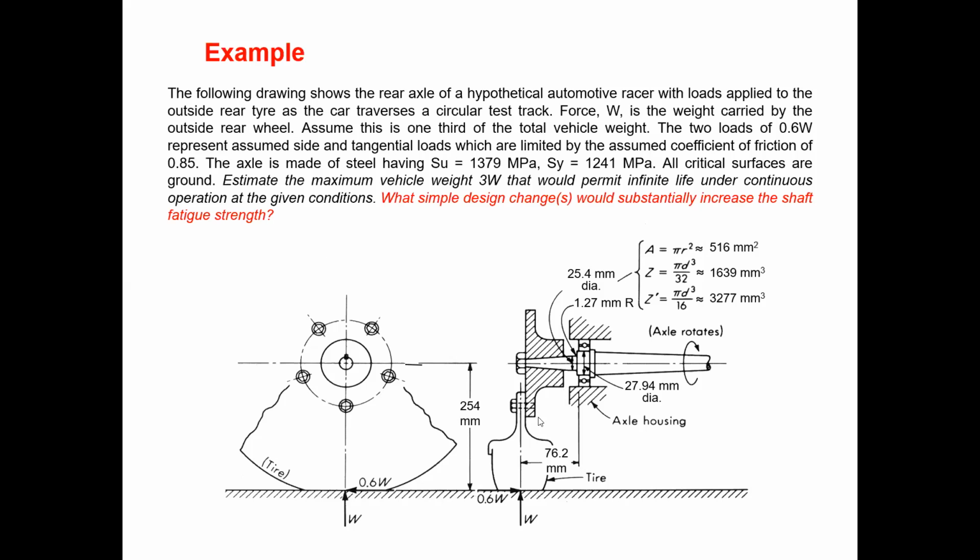So they are simple design changes. At that time you can't change the tire diameter or shaft diameter or the shaft length. What you can do is here. We always calculate all the things around here, isn't it? We calculate the stresses and K values that belong to here. So the shaft cross-section suddenly changes here. What you can do is put a smooth fillet here. You can machine it. Okay, that KT value you can change according to that.